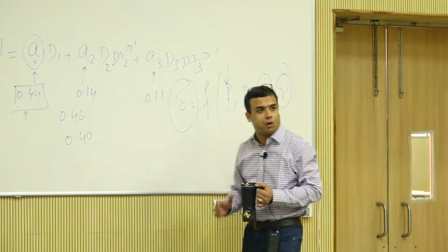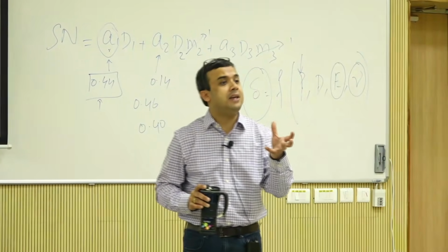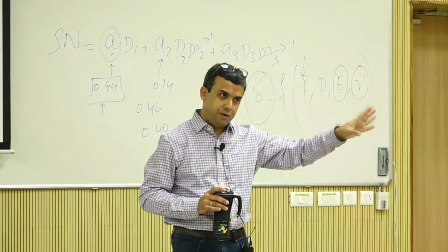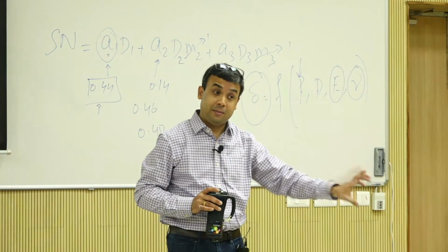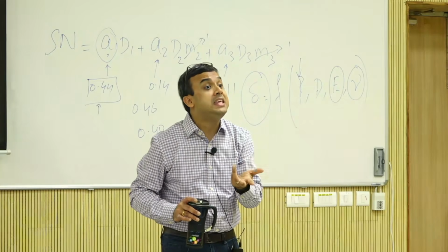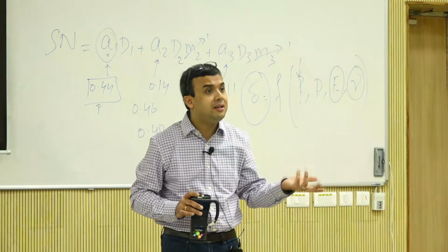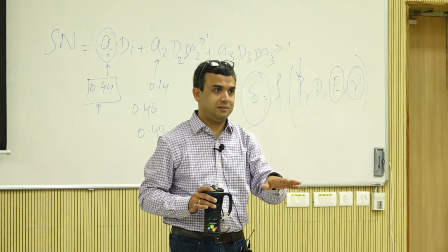That's the forward. Now let us say in a beam, I'm saying that I know load, I know deflection, I know I, which is a geometric property. I don't know E. Can you calculate E? You just rearrange the terms, right? That is back calculation.